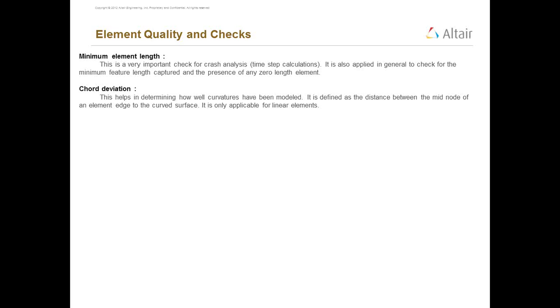Then chord deviation. This helps in determining how well curvatures have been modeled. It is defined as the distance between the midpoint of an element edge to the curved surface. It is not applicable for linear elements.